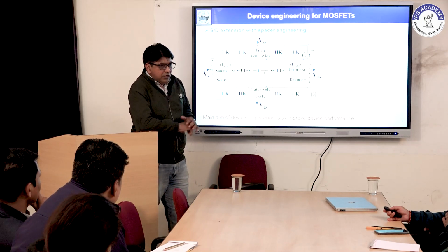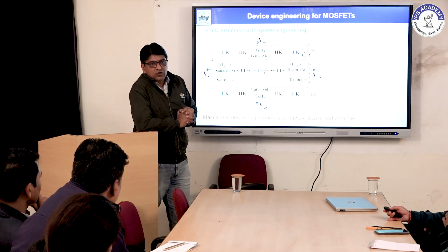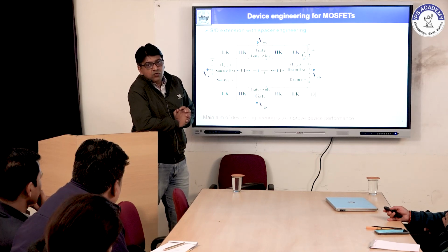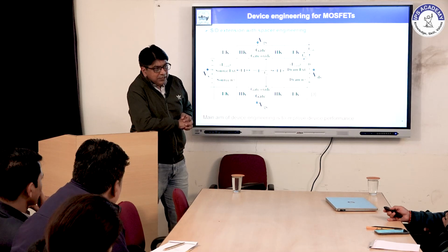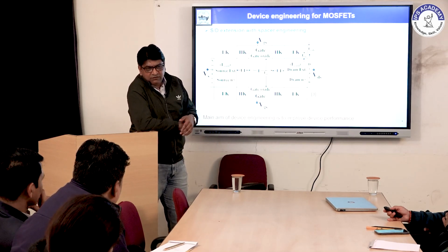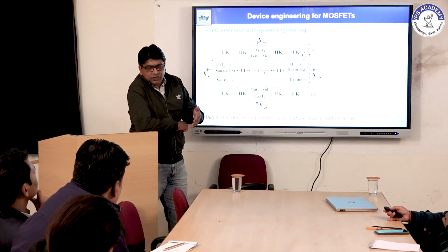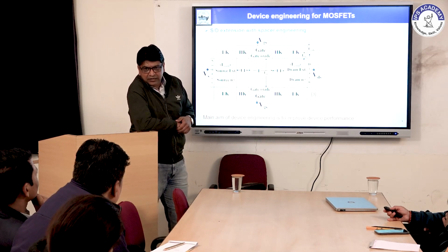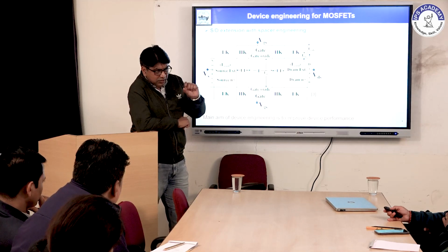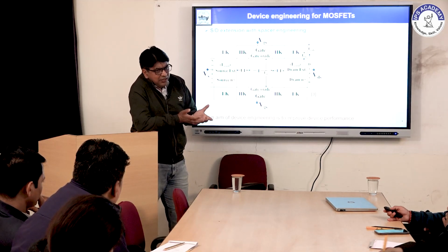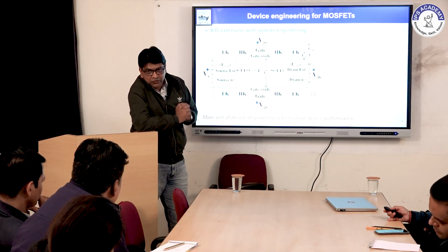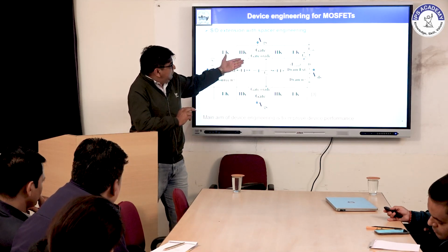So depending upon what technology you are working with, what issues there are, and how you can handle these issues, high-K dielectric is introduced as the gate oxide. Generally, we can use SiO2, but after 65 nanometer technology we start using high-K dielectric. If you increase the dielectric constant, definitely the leakage will reduce.